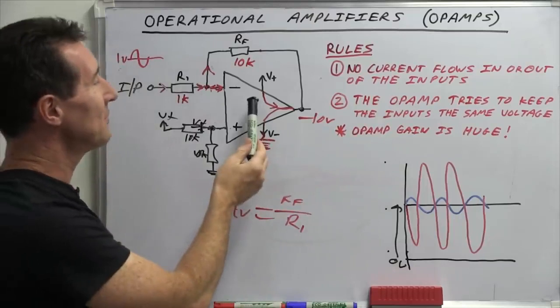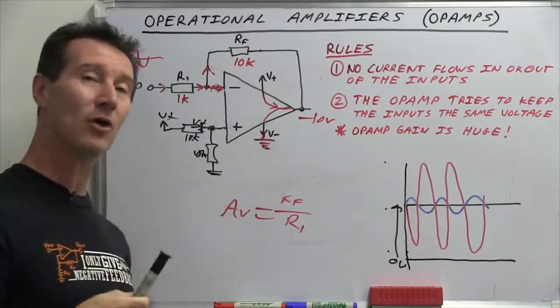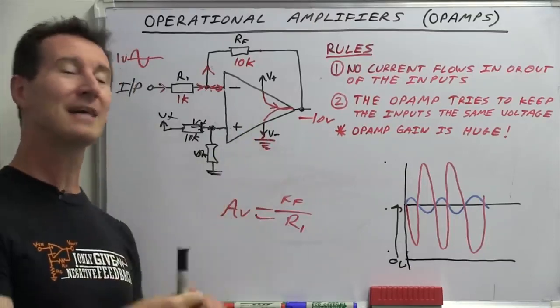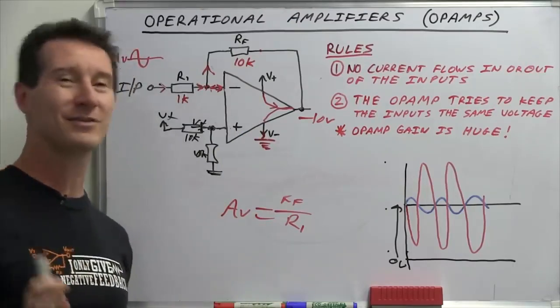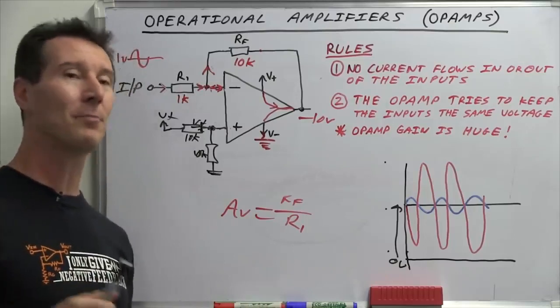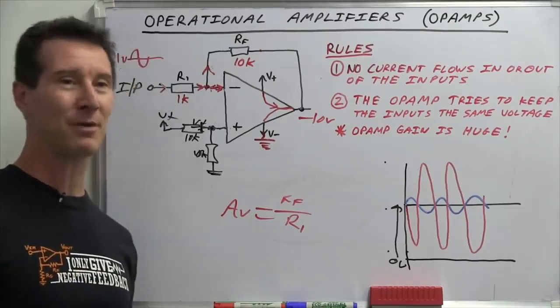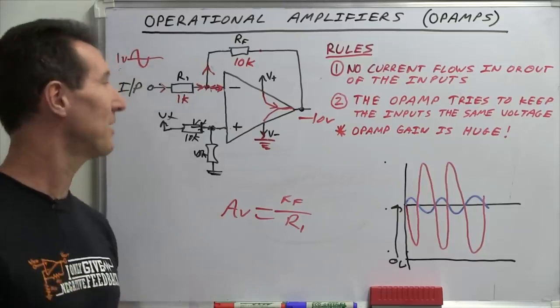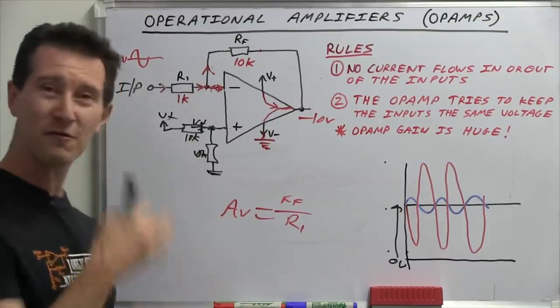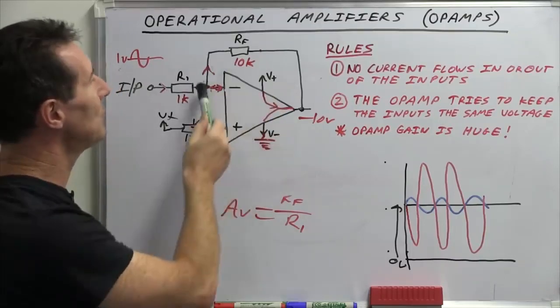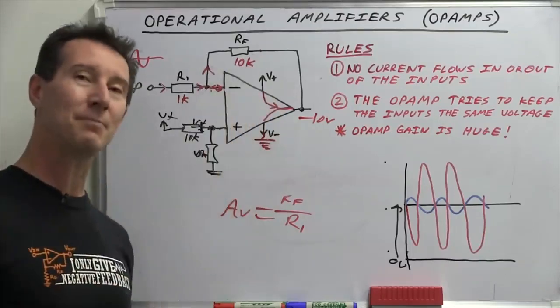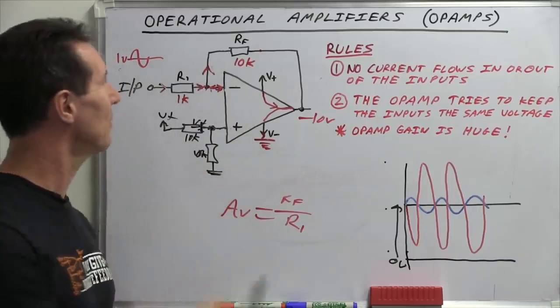But suffice it to say that an ideal op-amp that we've been looking at has an infinite bandwidth. It's infinite frequencies and signals, but in practice, no, of course not. Your practical op-amp might have a 1 megahertz bandwidth or a 100 kilohertz bandwidth or something like that. It could be a nice fast 100 megahertz, but it's always going to have a bandwidth which changes with your gain, or gain bandwidth product. And I've done a separate video, I'll link it in.